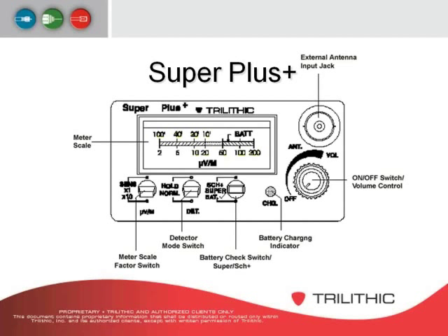That's very useful if you have your leakage detector docked in the truck, that you can quickly glance over and see what the leakage level is, but just make sure that you're safe when you do it. There's also the battery check switch, which is to the right of the hold button.